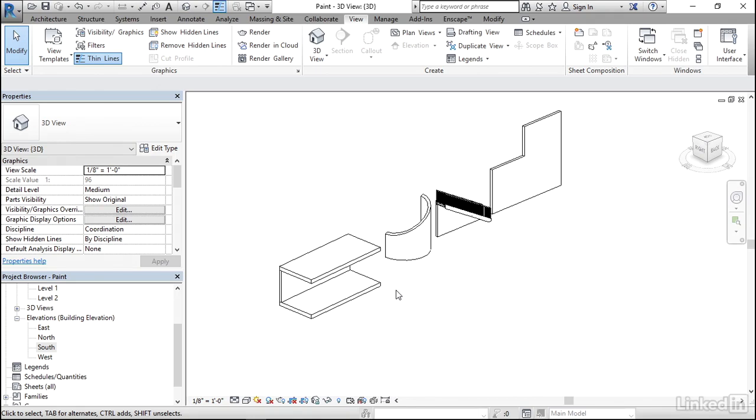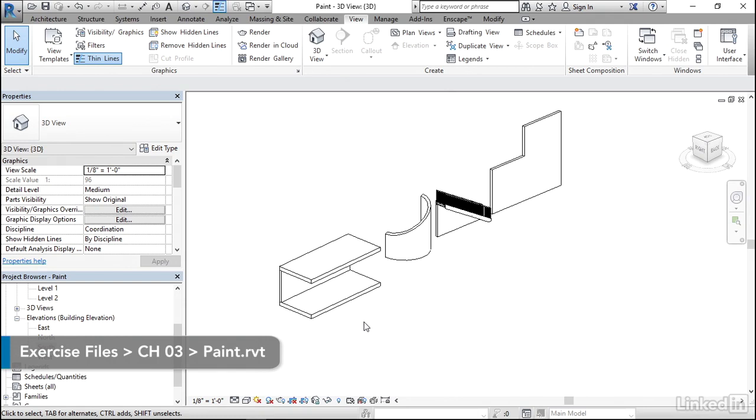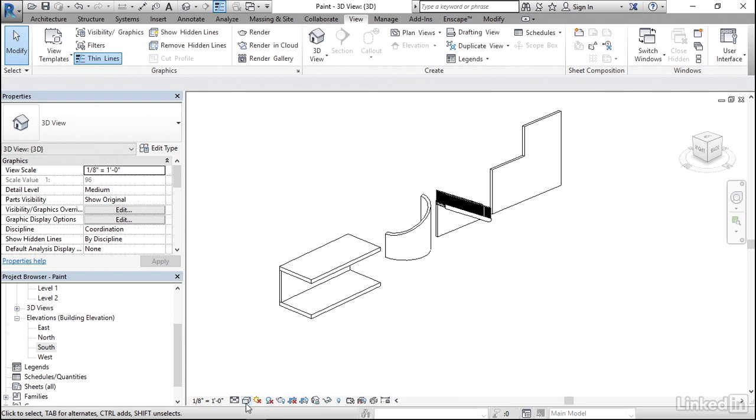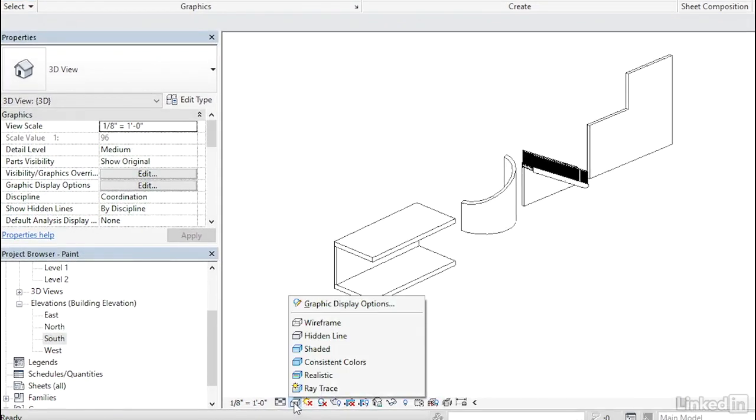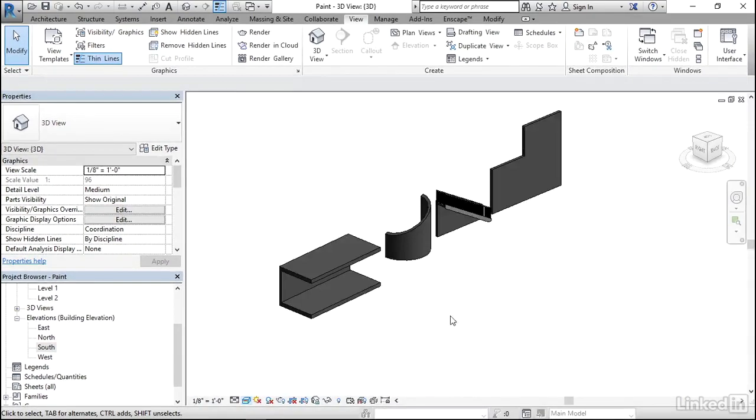Revit allows us to paint materials onto the faces of walls. To actually see this in action, from this view, what I'd like us to do is to come down on the screen to the visual styles, then turn on realistic mode. With as few walls as we have inside of the scene, this should run very quickly.